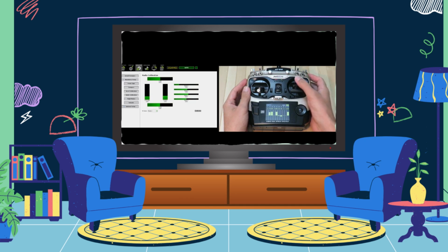On the left, you can see the controller and the percentage value of the numbers sent from each channel below it, while on the right, you can see the values read simultaneously by the flight card. For example, in the throttle channel, which we use to determine power, a value of 1091 is read when it's at the bottom. When it's at the top, a value of 1924 is read. This means that if the controller sends a value of 1924 on that channel, the power board will provide full power to the motors, and if the value drops to 1091, the motors will stop.